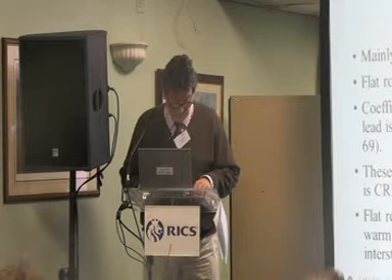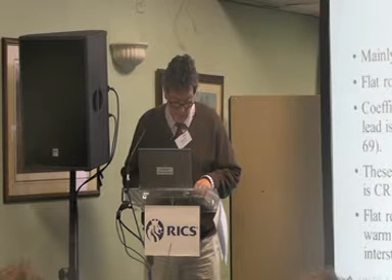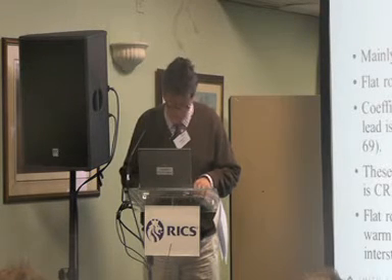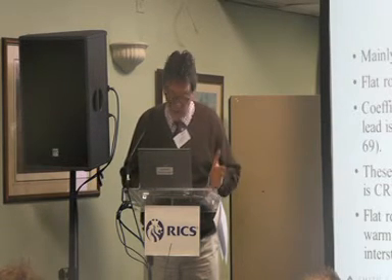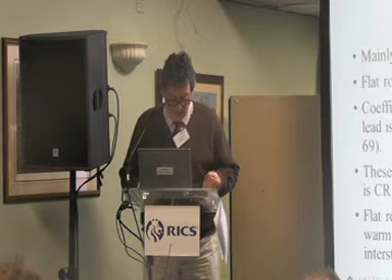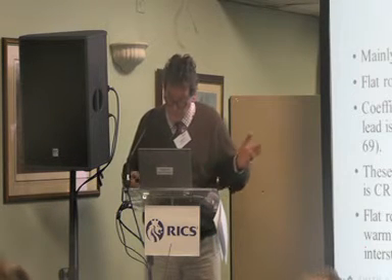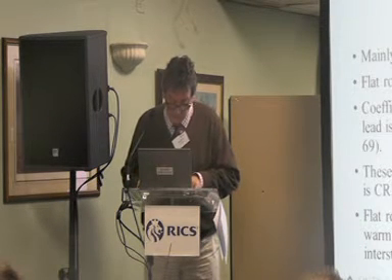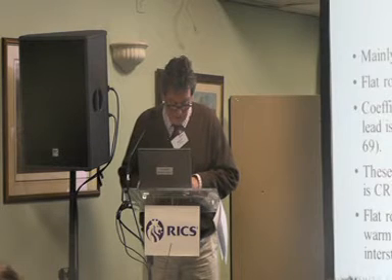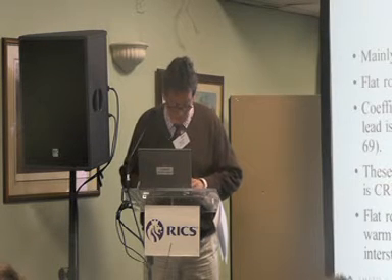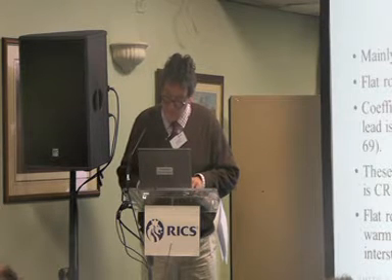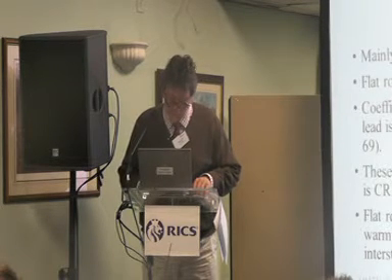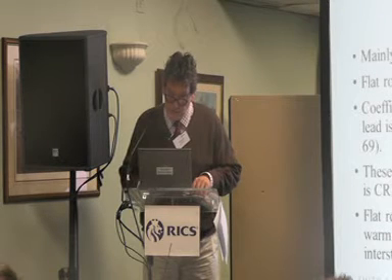And both these materials have quite large coefficients of linear expansion at around 20 degrees. I'm not going to go into the technical of that, but in effect, if you compare quartz, which is very stable, 0.3, water, which is not stable, it freezes and expands and moves thermally, 69. Lead is 29, copper is 17. They're both quite mobile materials. So these materials must be allowed to move. Bay size is critical, as is a suitable underfelt slip plane. So you give it a slip plane on which to move, and you allow it to move.